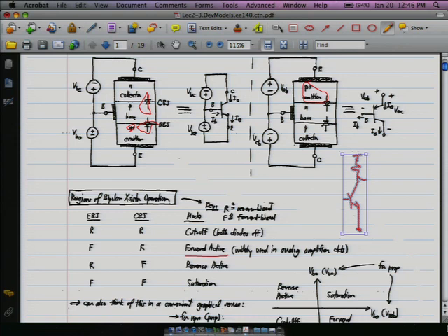The important thing isn't necessarily that this diode is explicitly reverse biased, but that it's just not forward biased. As long as the voltage across here isn't enough to forward bias this diode, turn it on, then we're generally OK, which means that this node might be able to swing down to something like 0.2 volts.